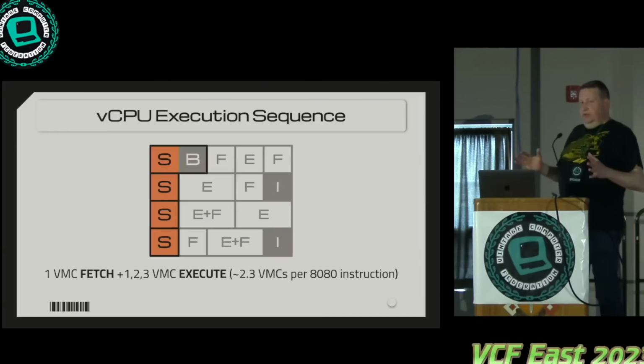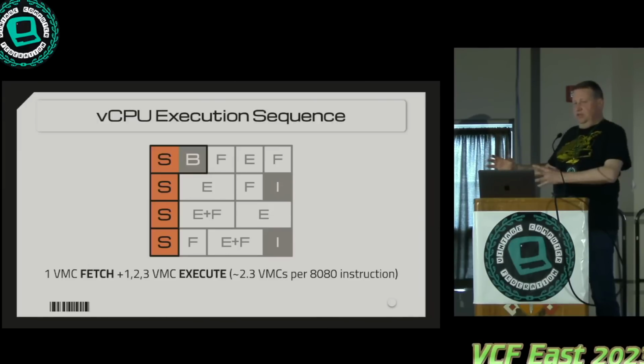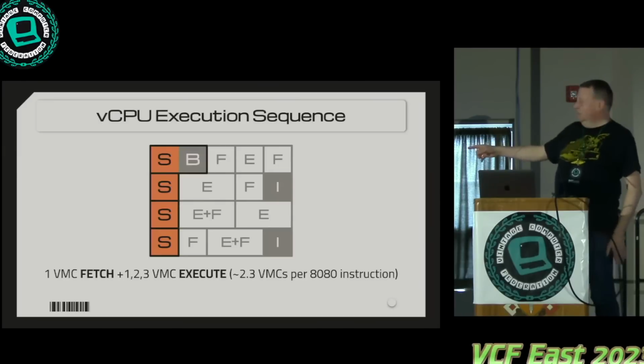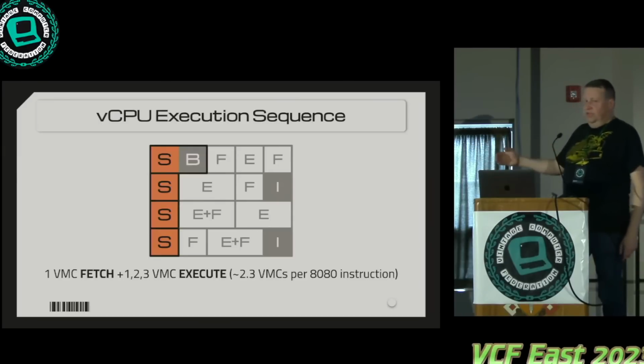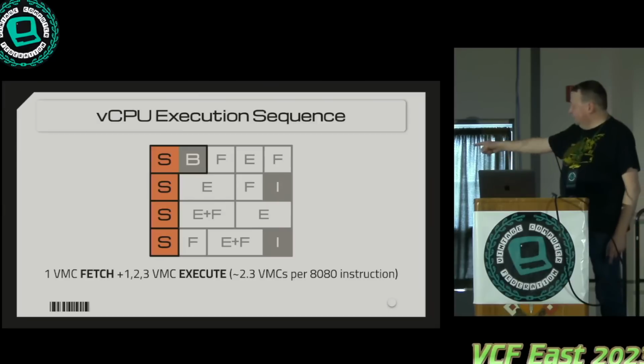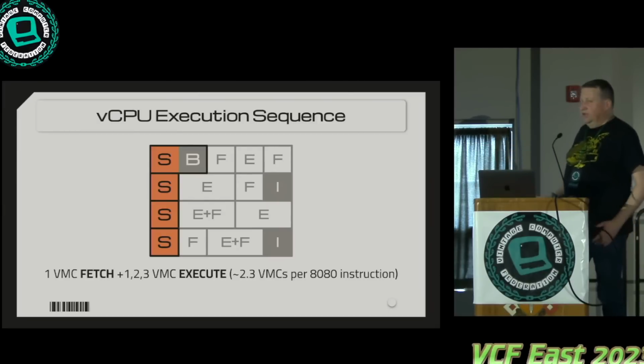But there might be a little bit of room, because what you'd have to do is pack the code to fit in these kind of blocks. But sometimes you have some space at the end, and you can prefetch the next instruction. So some of these, they'll do the execute, and then they'll prefetch. So you go straight back to the execute. So there's quite a few that are like that. So there's some where it does fit into that 43. Some it's a little bit too big, but not huge, so you can then prefetch.